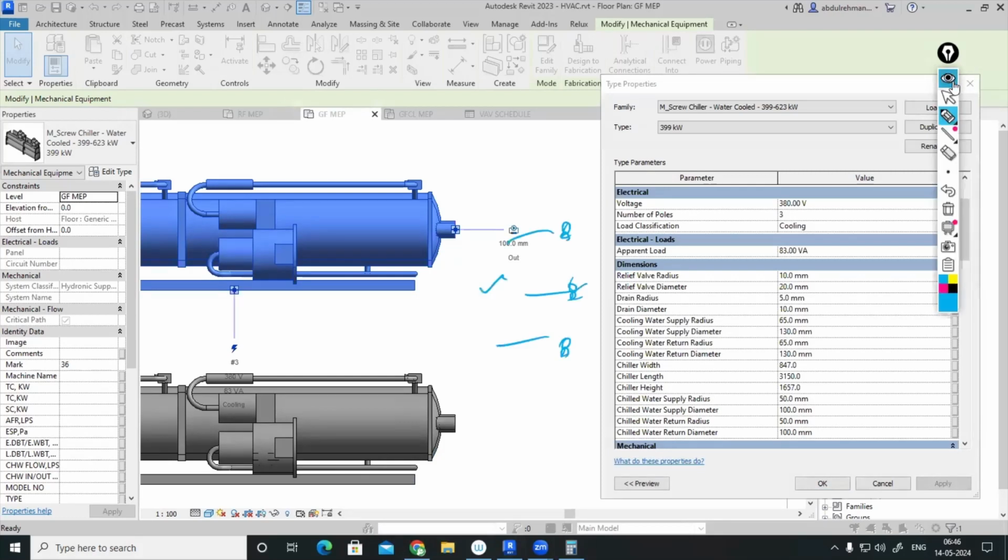For example, after the heat load, how much ton of refrigeration you are getting, with respect to 100 Pascal per meter to 400 Pascal per meter, maintain the velocity up to 1.2 meter per second or 4 feet per second for 50 mm pipe. Above 50 mm, from 65 mm onwards, the velocity maximum you can go up to 3 meter per second or 10 feet per second. Based on that, you can do it either from the chart or with the help of a pipe sizer.